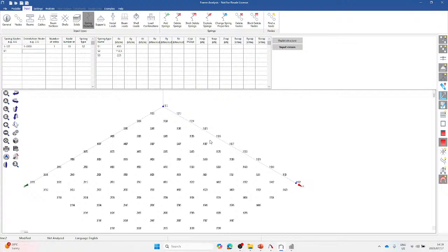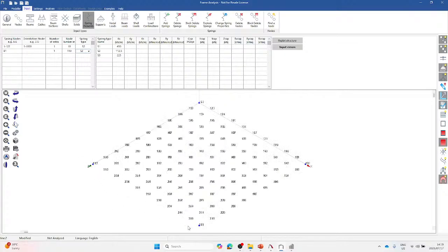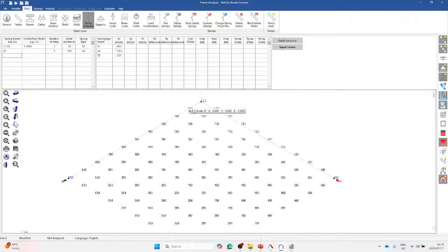And then from there, it is B1. So we're going to block copy these two nodes to these two edge nodes. So we're going to use the block copy. So block copy line 1, and that is 1. And then the difference should be 110, and that is S2. So you see, now that is being copied over, and then we are going to create for the edge nodes. So from this one, it is 12 to 123.